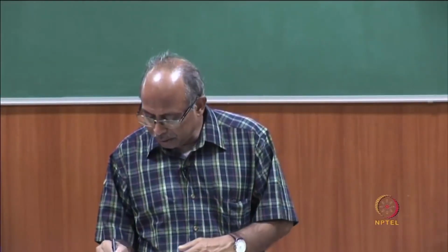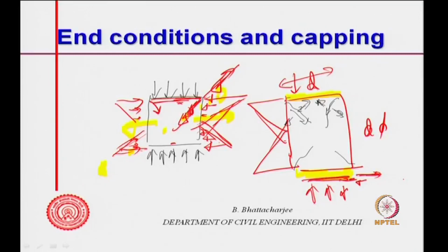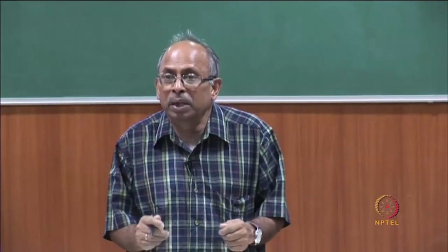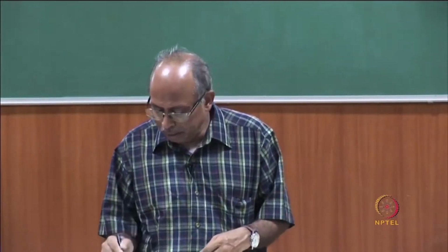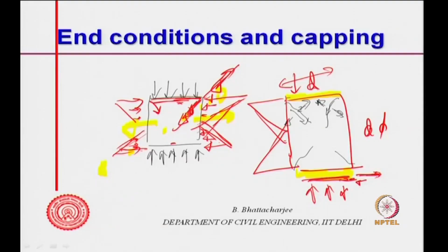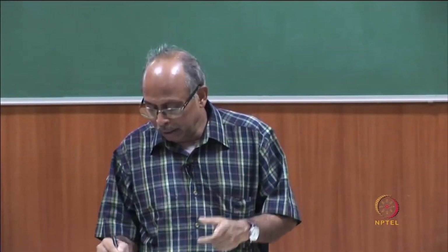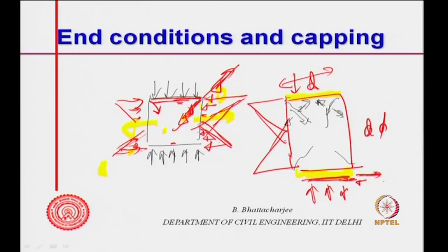If it moves quite a bit compared to its stiffness, which is a material property, then for a given force, supposing I have two different cappings, the more it moves along this direction, the more it will cause the concrete to move along this direction. If it is stiff, then the strain in this direction itself will be low, therefore, Poisson's effect will be minimal.